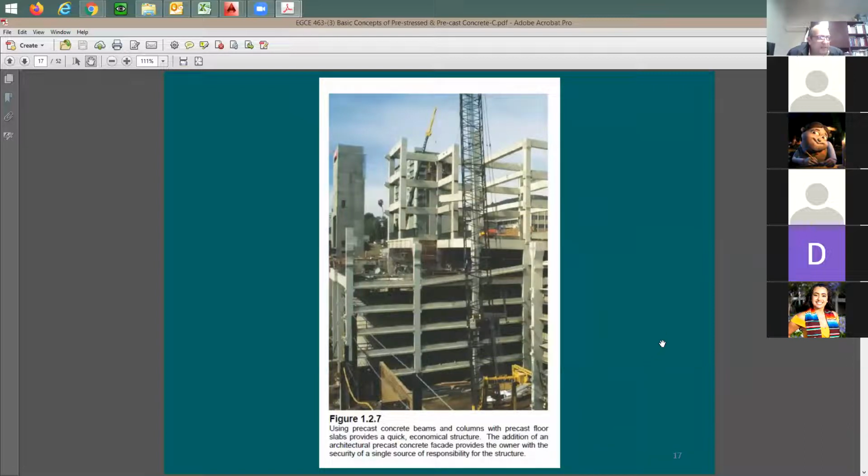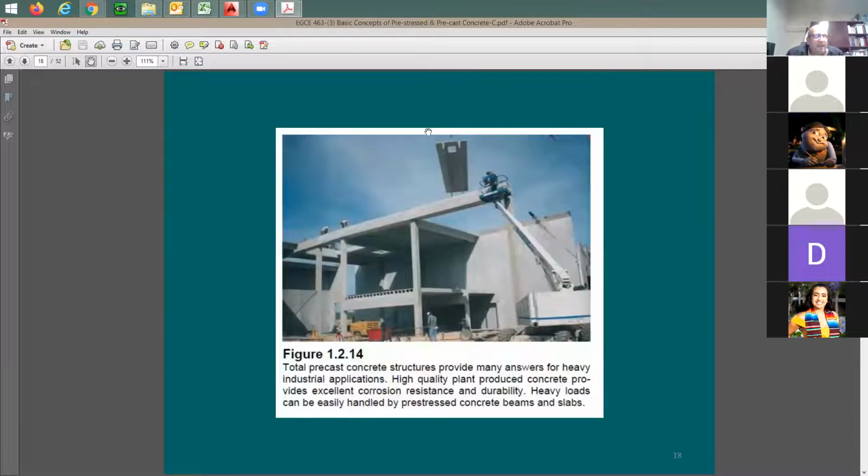This is a famous building, and if you look here, the concrete columns usually come as 5-story columns. This kind of optimum design is to have 5-story columns. And then you're going to have spandrels, inverted T-beams, and after that you can put planks, or you can put hollow core deck, or you can put double T's. Here's a double T. This is what I was talking about. You have two stems or two webs, if you like, and then a concrete slab. You just carry it and put it in place. It's very fast. Look at this.